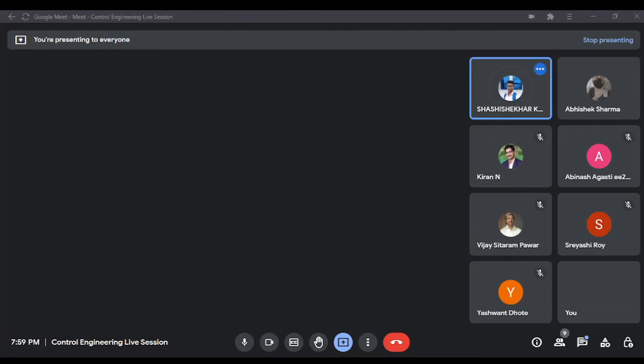The next controller is GC2 equal to S plus 6. TC2 will be feedback of G into GC2 with 1. This is the new closed loop transfer function. Here again we'll do stepinfo TC2. You can see settling time is less than 1 second, that's good, but overshoot is 31%, and we want that to be less than 5%.